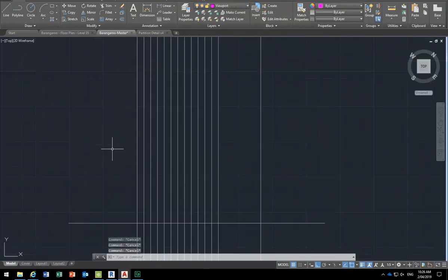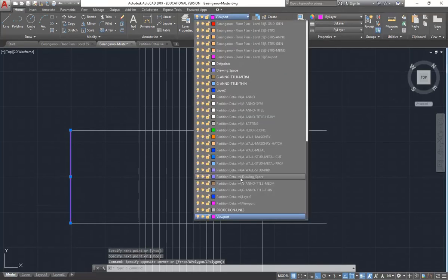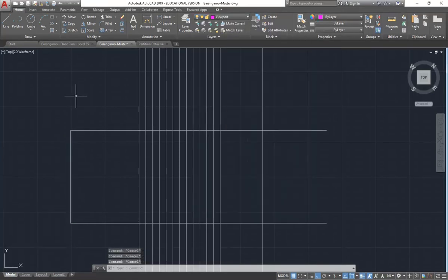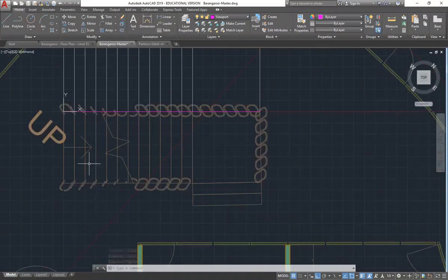So let's work out the height. I'm going to offset 3300, and then we can offset above, and then that's right. You'll see, do a bit of trimming, but mostly I'm going to use copying. Okay, so we need to know how many steps are in the staircase. 8, 9, 10, 11, 12, 13, 14, 15. They're not all showing, so let's say 18. Let's try that.